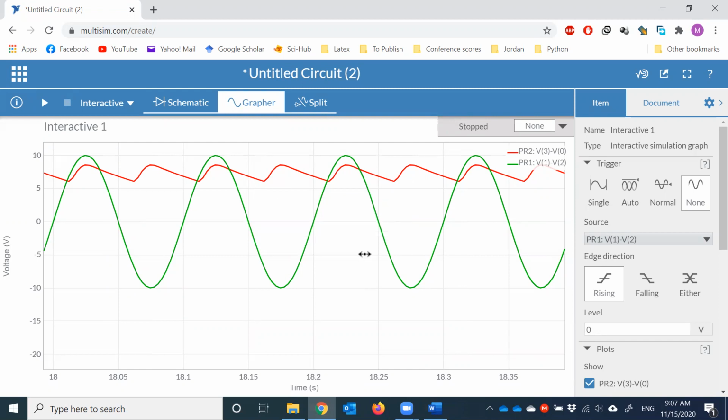Now, if you compare it to the half-wave rectifier, the signal was going all the way down, then charge up, and so on. Go all the way down, charge, and so on. In this one here, we have better, let's say, DC kind of signal. Because in the half-wave rectifier, this portion here will not exist. It's just only going to descend all the way to here and go up again.